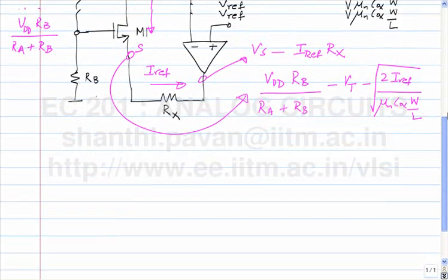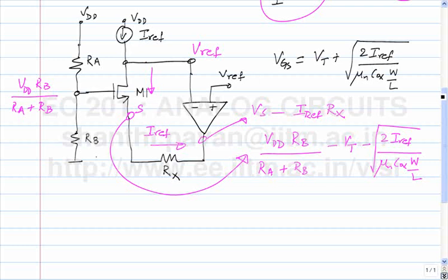How is it that we didn't need an op amp in the first 2 cases, but now we do need an op amp? Very good. Okay. So what he points out is that in the first 2 cases where we measured the current in the drain and applied current correction at the gate, when we did the comparison process, the voltage at the drain was increasing, which also happened to be the same direction in which the gate had to be moved. So you could do without an op amp.